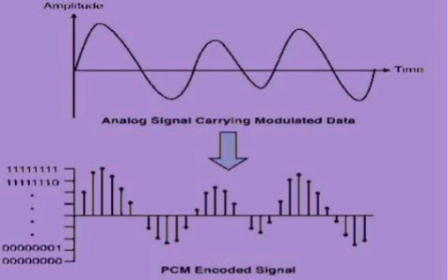Properties of autocorrelation function Rx of tau. Rx of tau is an even function, that is Rx of tau equal to Rx of minus tau. The maximum absolute value of Rx of tau is achieved at tau equals 0, that is Rx of tau less than or equal to Rx of 0. If for some t naught we have Rx of t naught equal to Rx of 0, then for all integers k, Rx of k t naught equal to Rx of 0.